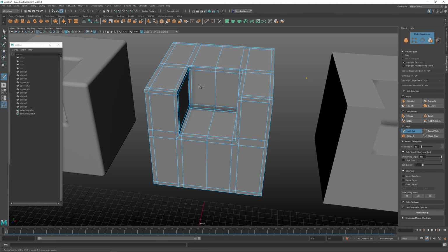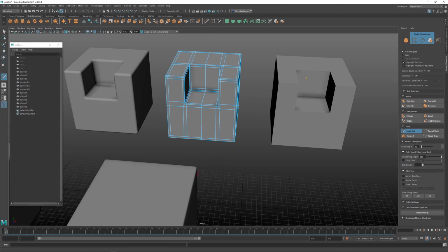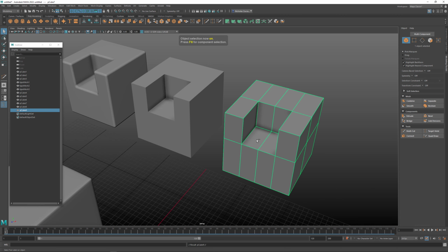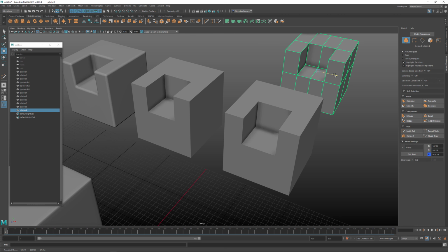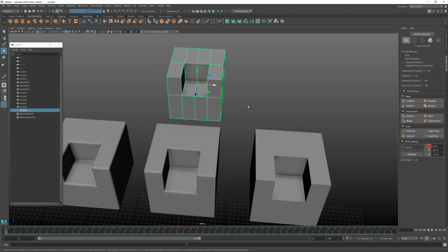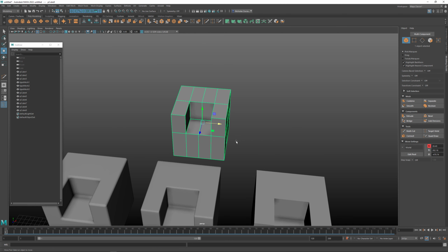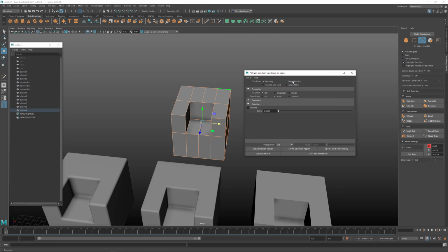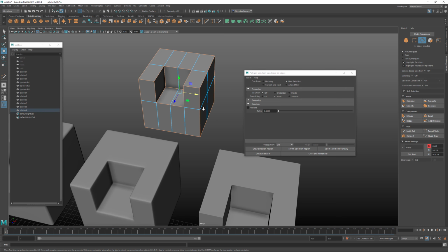So I wanted to show you this as well. Let's go out of this tool, and I need this object. Let's duplicate it, move it back like this. Let's tap 3 for this one just to leave that on. And we'll move this over here. And if you remember our selection type for this, let's hit F10 and select this. And we're selecting all of our edges, and let's go to select and then use constraints. We'll do next selection, and it should remember this hard selection. So we've just selected this here. Okay. And we're going to hit Control B to bevel, or we can shift right click and say bevel edge.